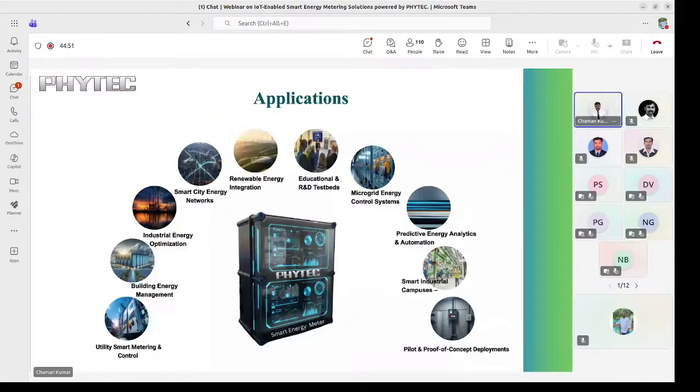So this is all the power line communication protocol, where we have smart meter devices, and then we have this IT900 modem, that is a wireline chip. Using that chip, the data will go over the wire to the DCU and then to the cloud. And from the cloud, we will control the meter. And these are the parameters of this IT900 chip, a 32-bit PLC SoC, 26.3 megahertz CPU, 33 KB RAM. So this is how the data goes over the power line. Wherever we get the power from, only that power line we will use to send the data, so that saves wire, basically.